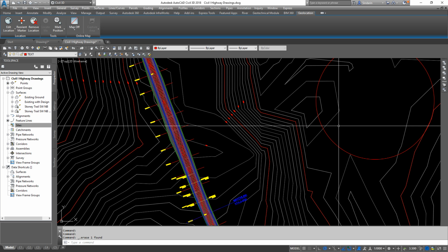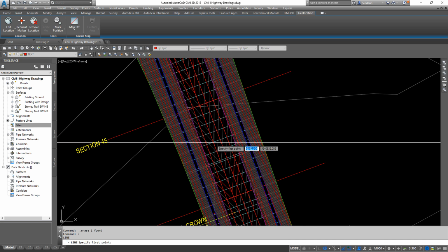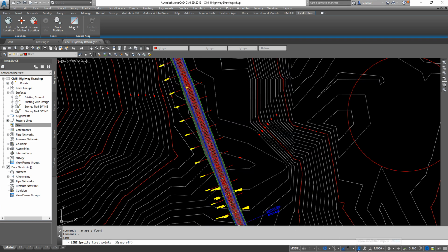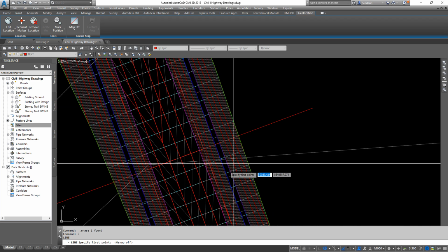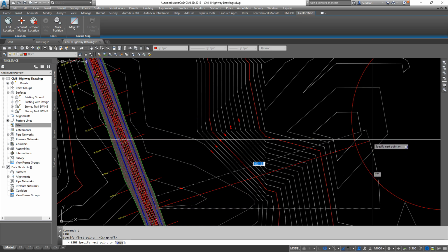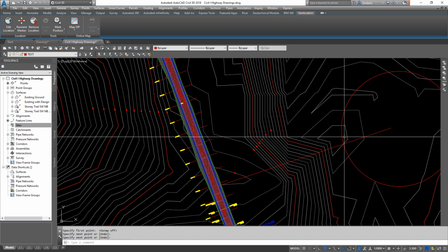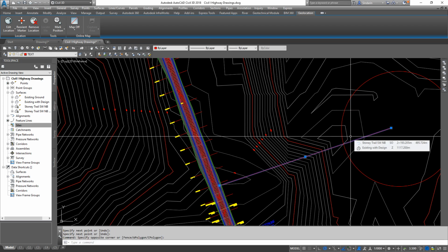And where that elevation of the ditch comes into the pond, so if I just draw a line here, and give me a second. Okay, I had to turn off O-snaps. O-snaps on a surface and with lots of line work around is intensive on the system and it causes lag. So if we were to figure this out just quickly, to draw a line from here to approximately where our pond would be, that's about 620 meters from the length of the line.